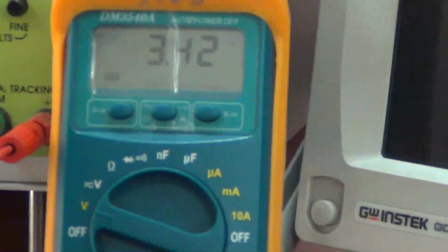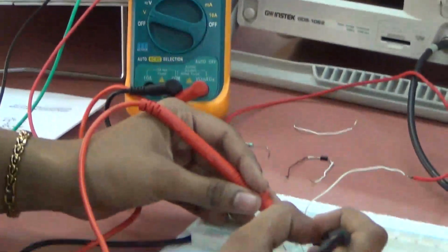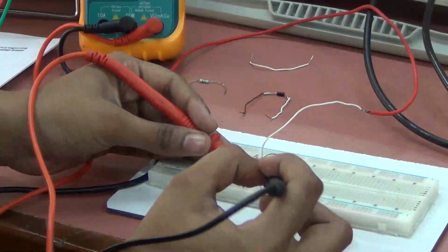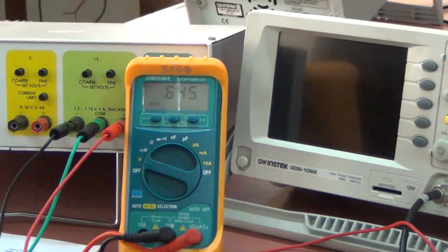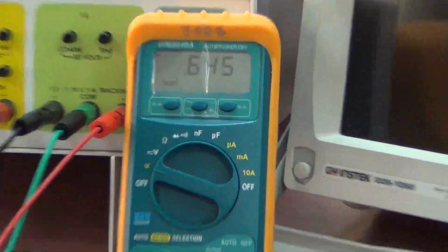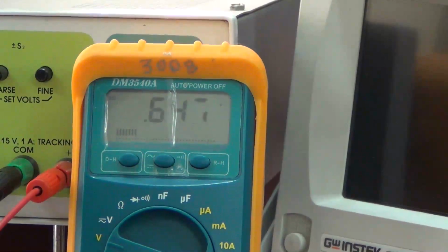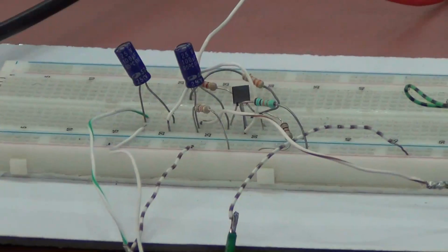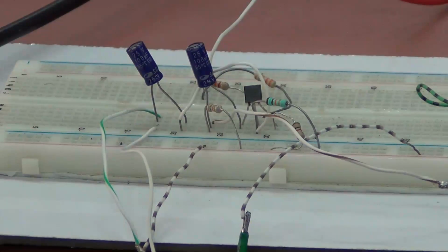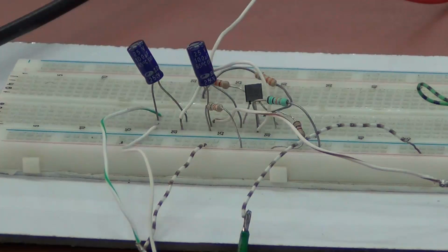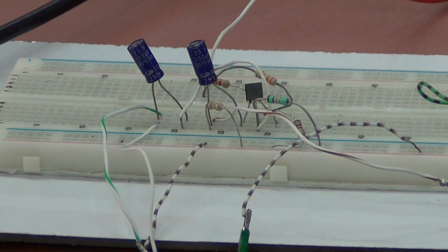Now we have to ensure that the transistor is in active mode. So we have to measure the voltage across the base and emitter junction. As you can see, the base emitter voltage is coming to be around 0.64 volt. So the transistor is acting in active mode. After measuring the node voltages VB, VC and VE, you are supposed to estimate the currents IB, IC and IE. Then you have to compare between the theoretical and the measured results you got. After that we will switch off the power supply and we will again come back to the circuit.